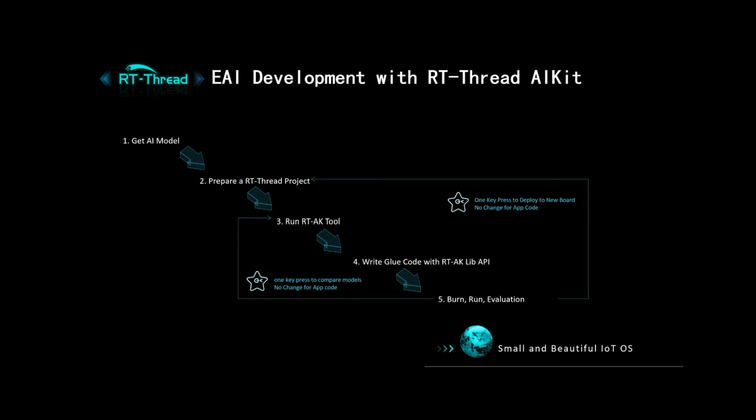So it's just about 4 or 5 lines of code to glue the RTI library. And we call that: find the model, call the model, get a result, just like that. Then we can compile a project, burn it to our device, run it, see if the result is good enough. If it is not, usually we have two kinds of workflow.